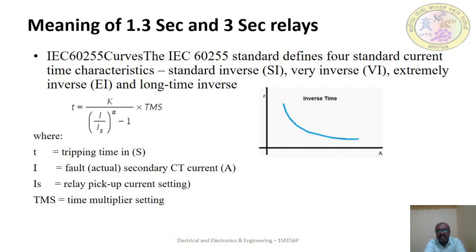This type of relay's operating time changes inversely with current, so a high current will operate the overcurrent relay faster than a low one. There are different types of relay settings, as you can see in the diagram. This is discrimination by both time and current. The relay operation time is inversely proportional to the fault current. The operating time of the relay can be made faster or slower by adjusting the time delay settings. The lower time delay settings give fast operating times, generally ranging from 0.5 to the slowest at 10.